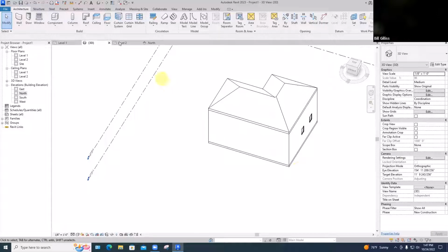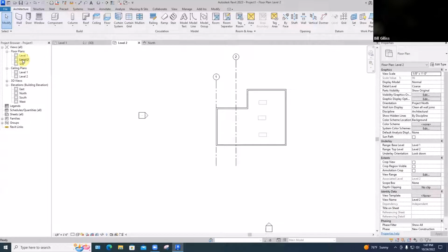Let me think about a second floor. And right now I don't have a second floor in there. I just have a first floor and all the way up to the roof. But if I go into my level 2 view, where you see I'm seeing faintly down to those desks on the first floor, I can go to floor, architectural.